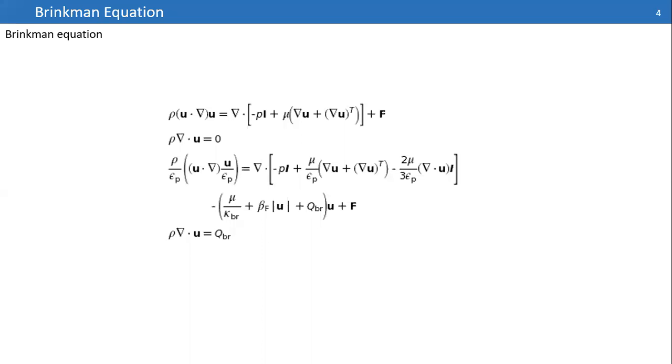range of void fraction can change, let's say around 20%, 25%, or 30% to 60%. It depends on the shape of the catalyst. For example, in hydrodesulfurization plants, I know that the void fraction is around 30%, and in a reforming plant it is around 50%. And you can consider the bed of the catalyst as a porous medium and solve those equations.